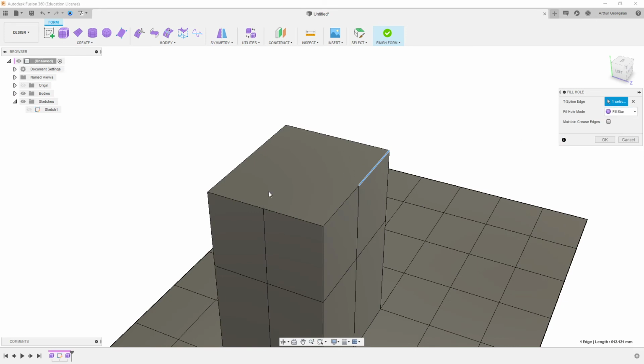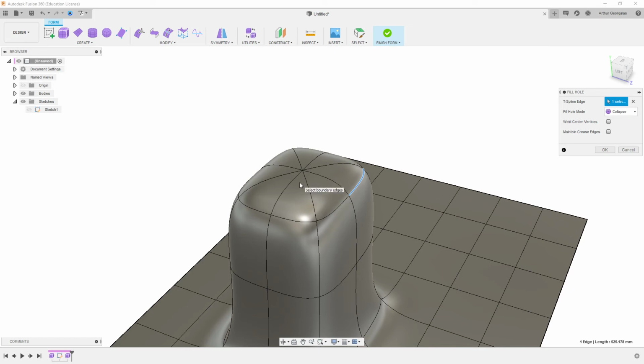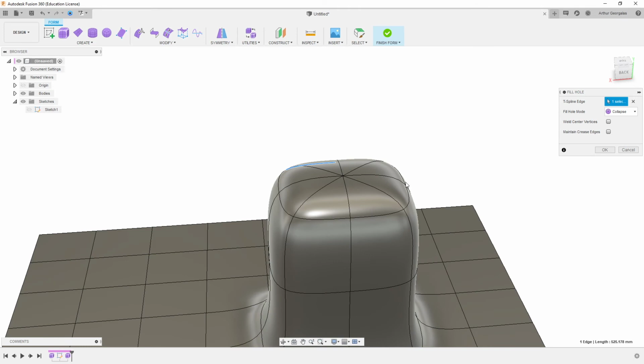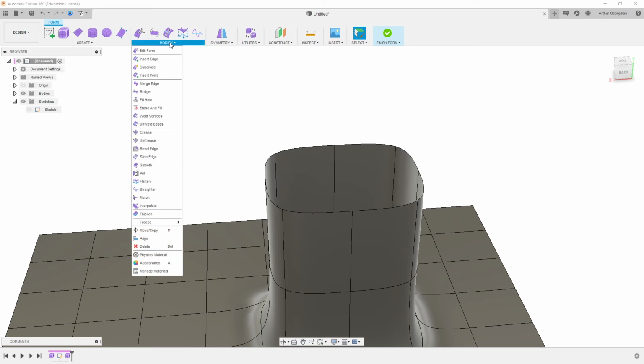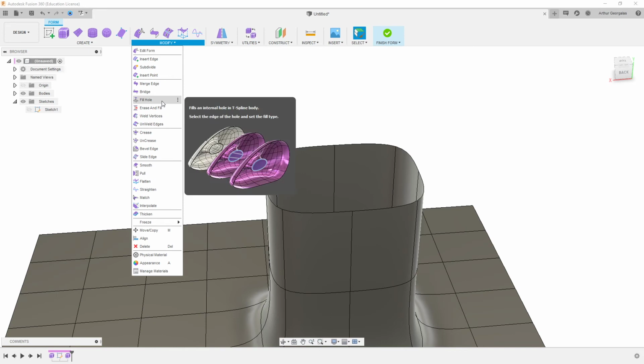Fill star simply makes an 8-sided star, which is really bad, and collapse brings it together like a sphere would, and we saw how that can cause problems when it's all in a point. So for me, what I would probably do is create a bridge from here to here, and then we have to weld in these edges. So this will be a really good way. I can show you the Weld Vertices command.